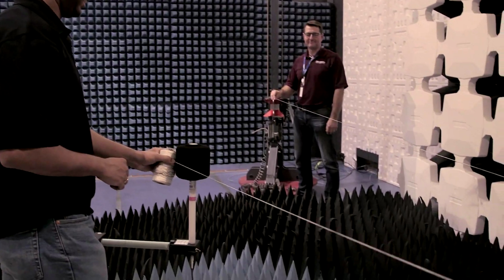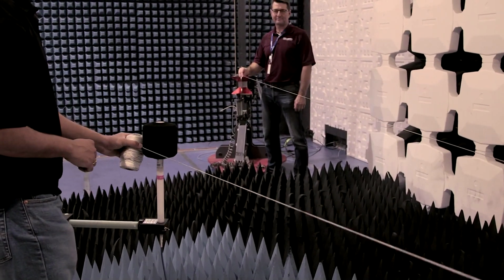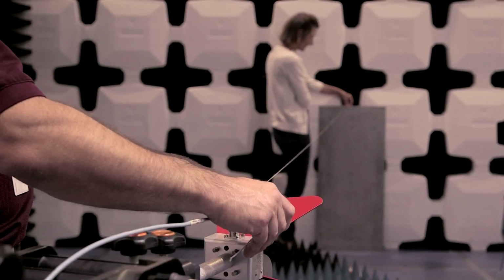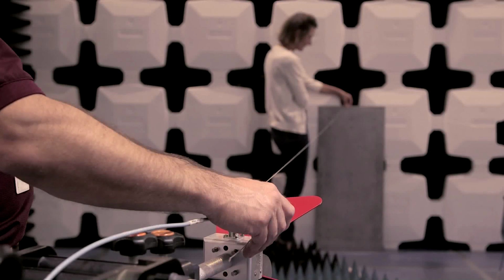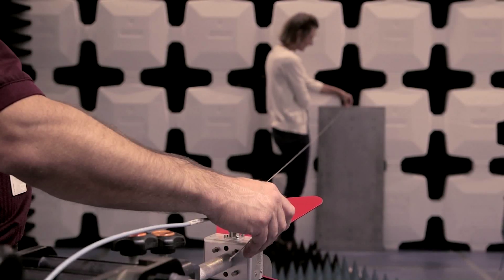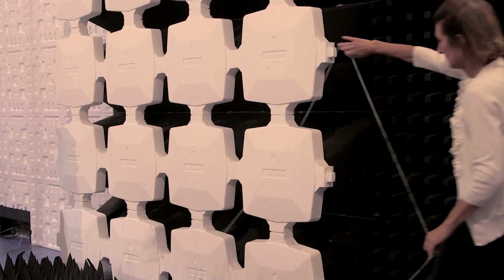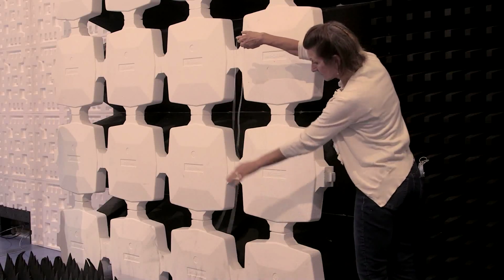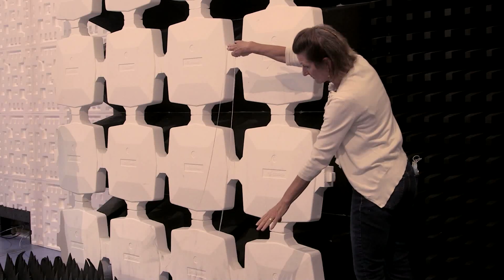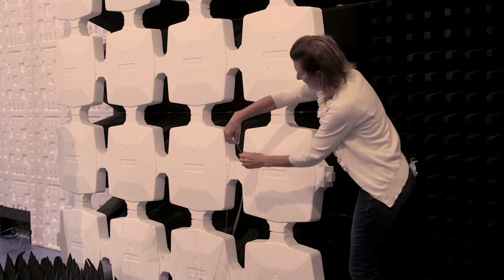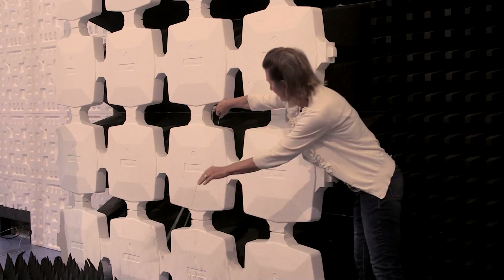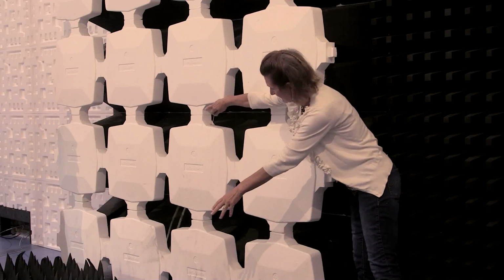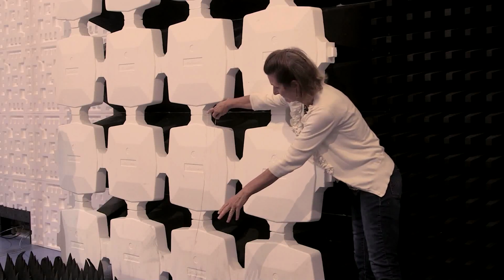And then we're going to attach one end of the string to the transmit antenna, another end of the string to the receive antenna, and then we're going to move this string so that it will basically touch either of the walls. If we go to the left wall, you can see that the string is not straight. It's hanging, so that tells us that this path length is too long for a reflection from the left wall.